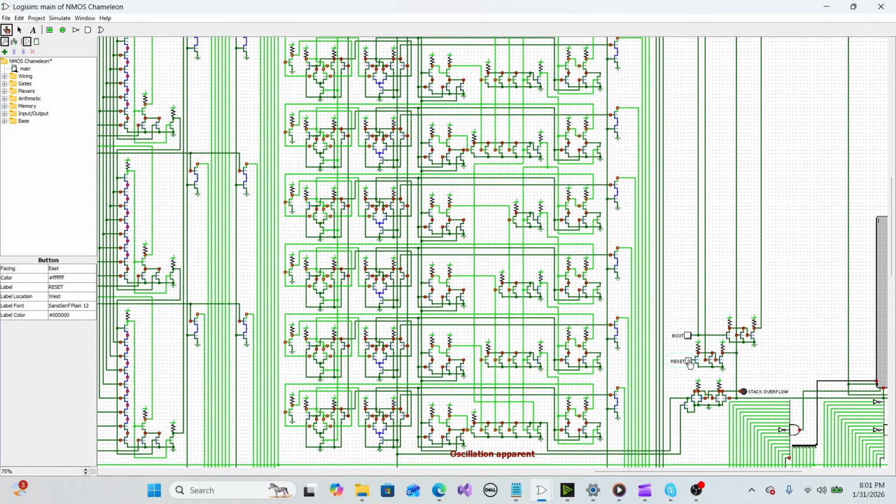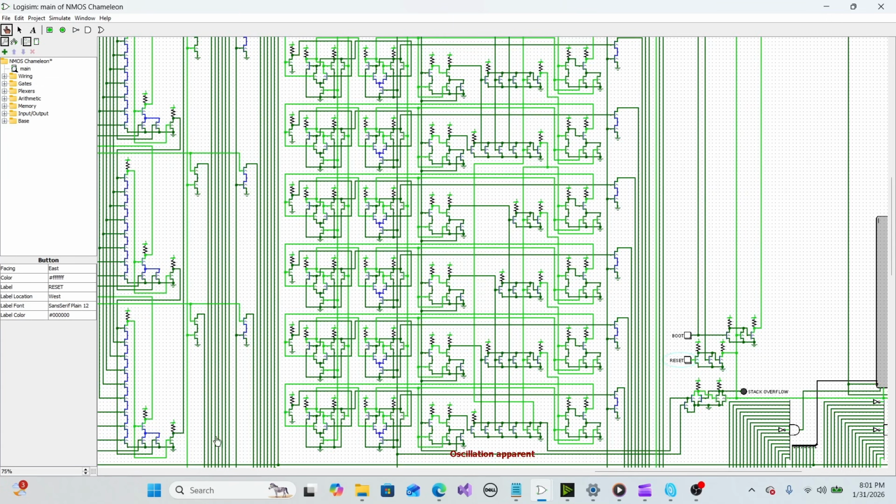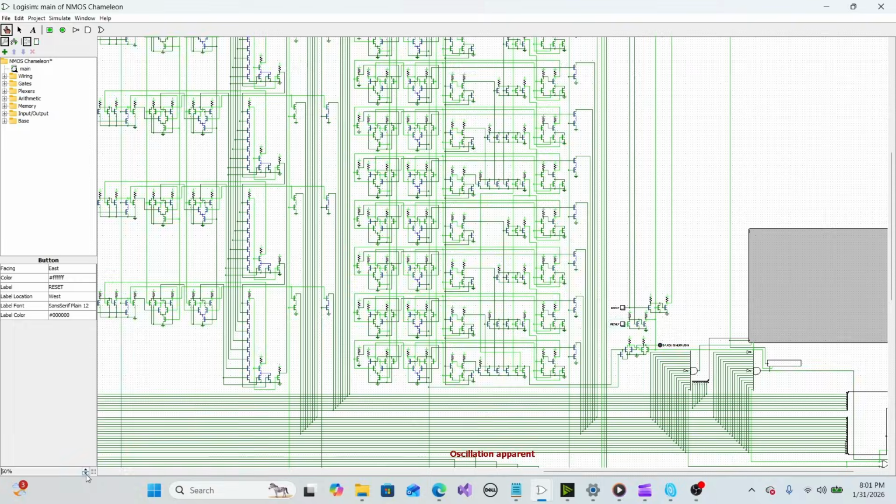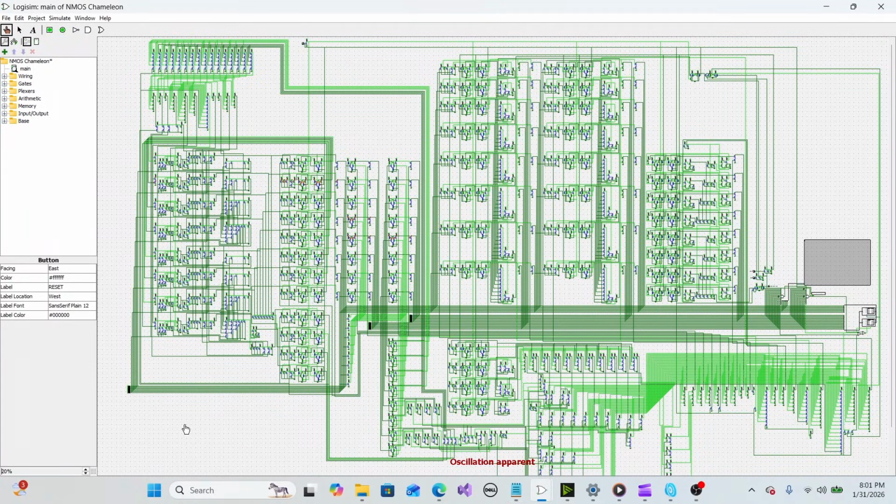while holding the reset button down on the circuit, we enable the simulation by pressing Ctrl-E. This will make it so that all of the latches connected to the reset signal get placed in a definite state. Many of the other latches will still be oscillating though, but since we have added noise to the component delays, we can simply re-enable the simulation by pressing Ctrl-E again. Some latches will still be oscillating, but there should be less than before. Now we can simply keep pressing Ctrl-E until all of the latches have settled into definite states.